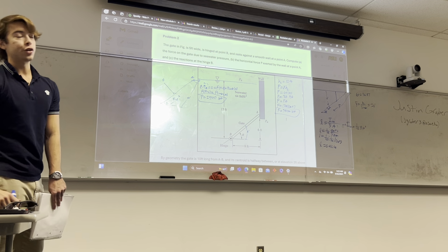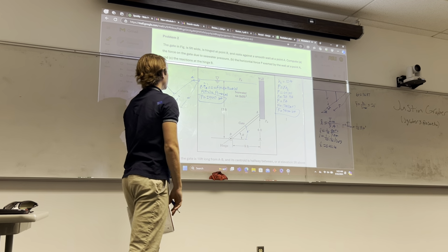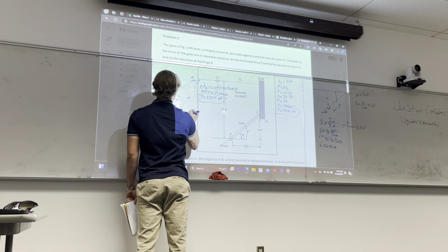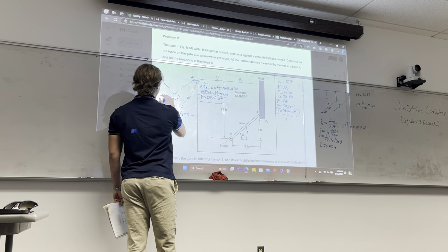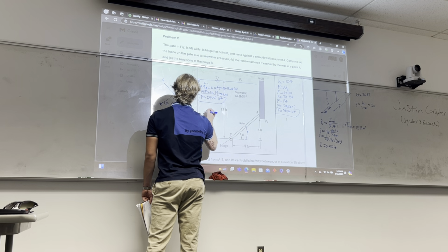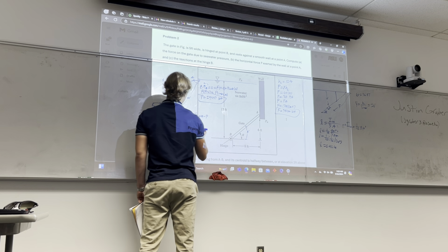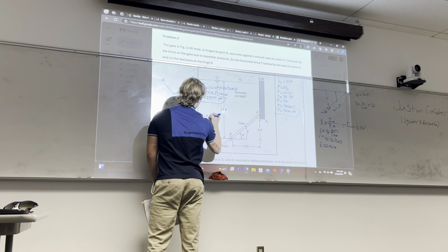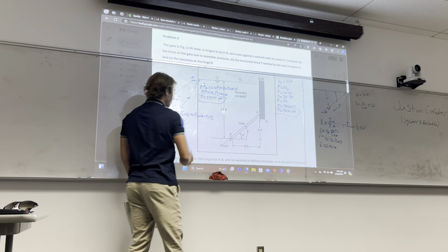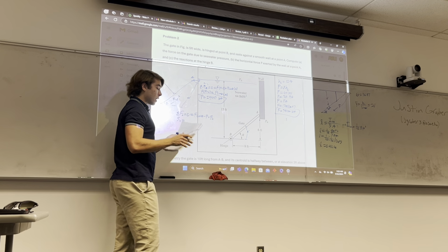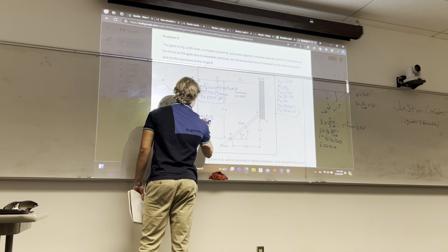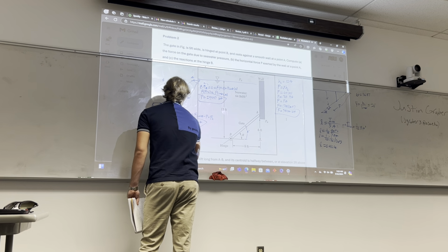Now, since we do know P, we can just do sum of moments. So just go back. Let's do sum of forces about X is 0 equals F cosine theta minus P, and oh yeah, plus BX. So once again, just plug in numbers. BX ends up equaling 6296.